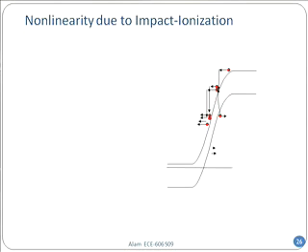And you can very quickly see that 1 to 2, 2 to 4, 4 to 8, 8 to 16. What is this progression? This is an exponential progression, a geometric progression. Therefore, a huge amount of current will start flowing through such a system. And this is called impact ionization. Impact ionization is also called an inverse Auger process, because Auger forces them to combine and go down. Here, electrons are being generated.